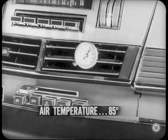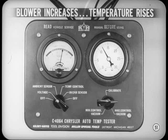Right, Jack. And at the transition point, the output air temperature should be at about 85 degrees, give or take 10 degrees. Then, as soon as the change is made, the blower starts to speed up, and the temperature continues to increase. As you continue moving the dial toward maximum vacuum, the blower will make 2 more increases in speed, and the output temperature will continue to rise.